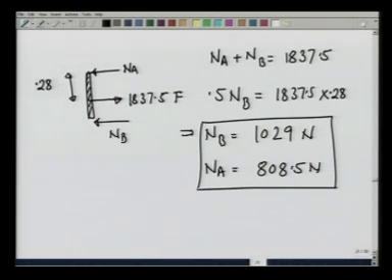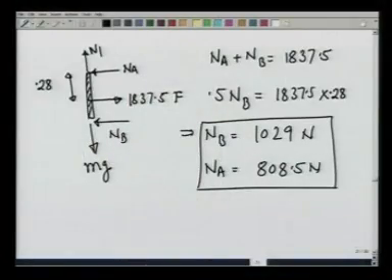If the door also had some weight, there would have been a reaction at A which would have nullified that weight mg. So, you see how we have calculated the forces due to water pressure on the door and consequent reactions on the hinge holding the door and on the wedge which is not letting the door come out.